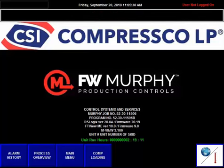Here we're selecting Unit B, English. Just below you can see Unit B, Spanish. We push the Restore and Download button. Now you can see all the Unit B P&ID tags and the language is populated.